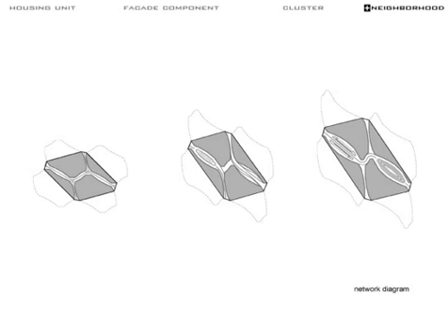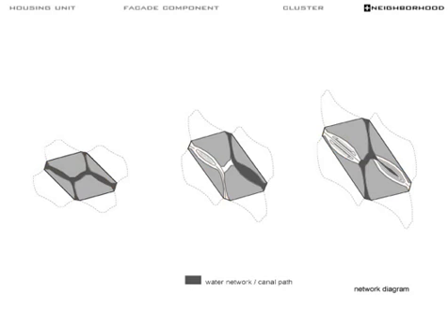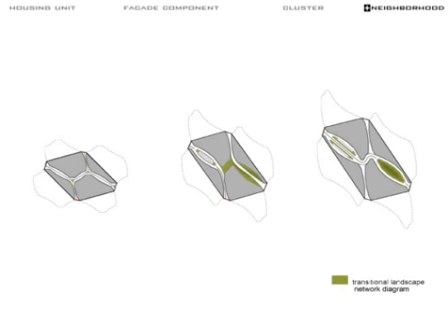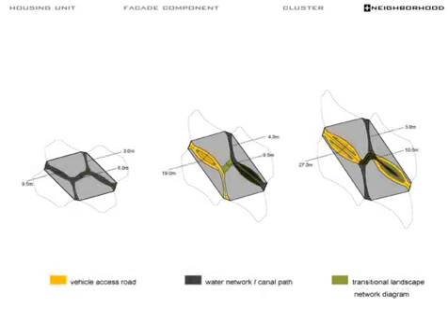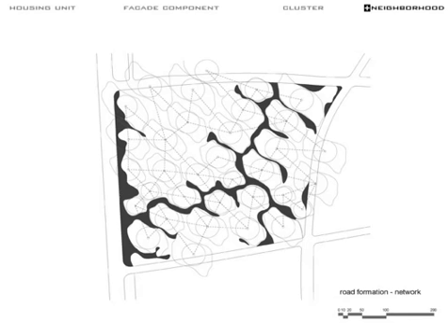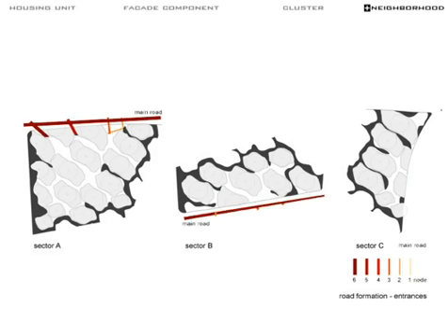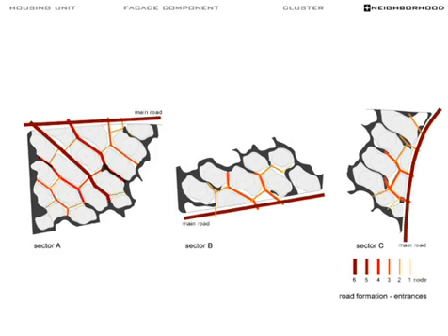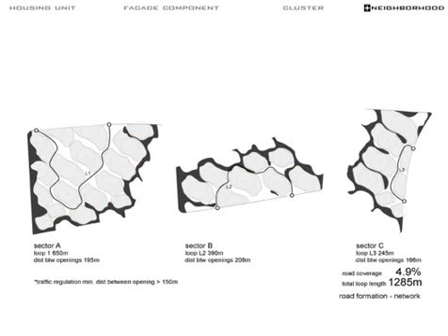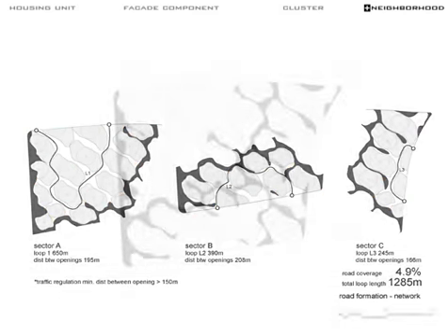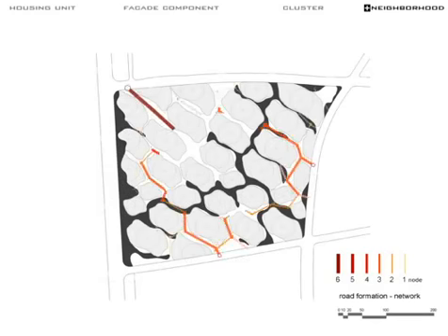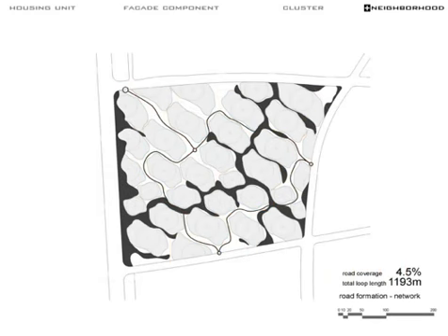To complete this neighborhood model, 3 networks are considered. This includes road infrastructure, water infrastructure, and landscape elements that transit between the wet and dry territories. The wider the width between the cluster formations, the more possible layers of networks can be implanted into the system. Taking the canals as the boundaries, vehicle access roads are firstly evaluated through the hierarchy of number of intersection nodes for the 3 sectors. To minimize coverage for vehicle roads, in each sector as independent traffic loops, secondary detours are integrated into the network for connectivity and distribution.